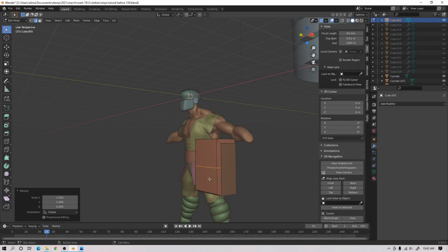I'm going to move my mouse beneath this line, press V, so this is ripped. Left click, right? I'm going to go to face select, hover here, press L. When you press L and hover over a separate object, it tends to select the entire object. We're going to press X, then choose faces to delete.